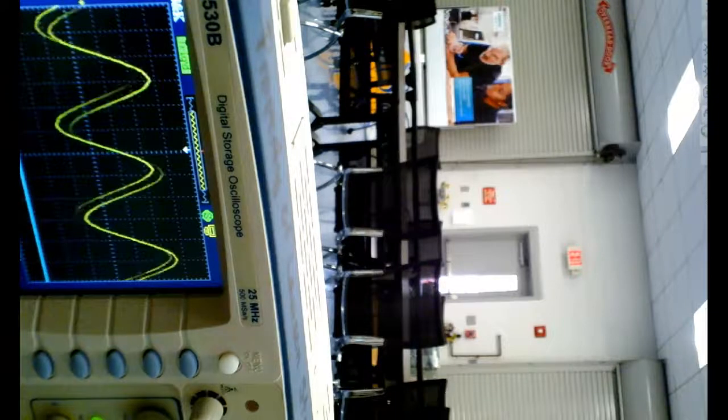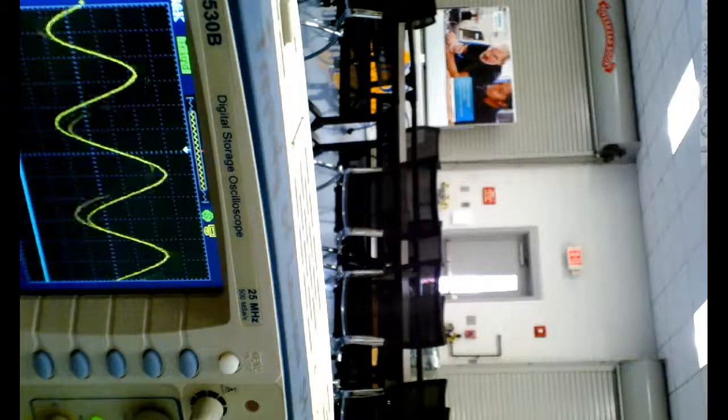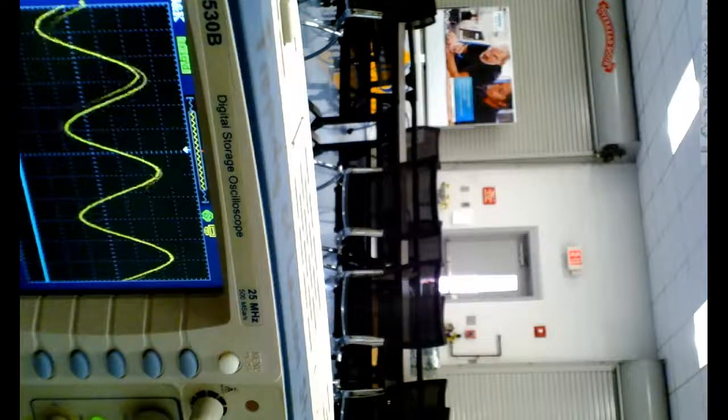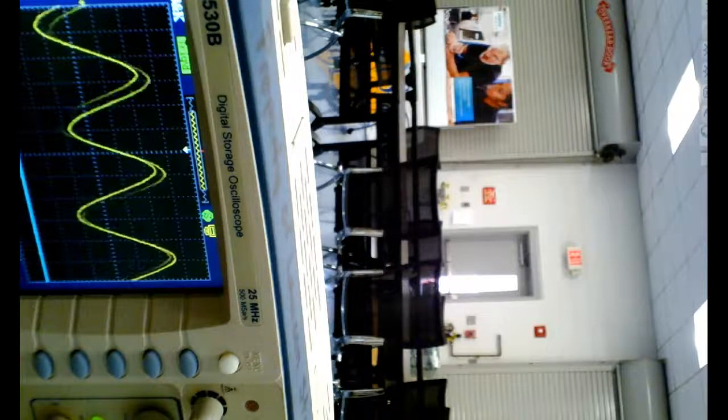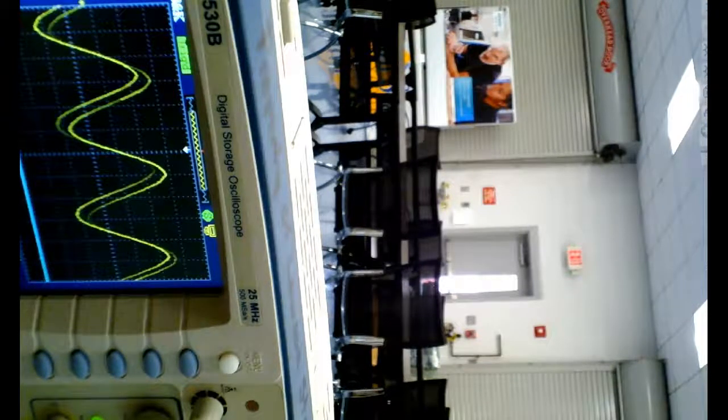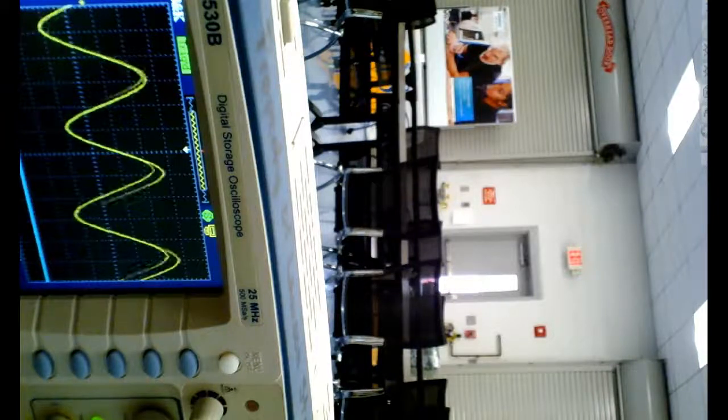That's one of the ways we check the scope probe, is we just touch it with our finger, and you'll see 60 cycle, because it's picking up me as a capacitor, which is pretty neat. So that's my capacitor right there. So if I can take this and run it into an electronic circuit that sees that change and then triggers a digital output, then we have a capacitive sensor.